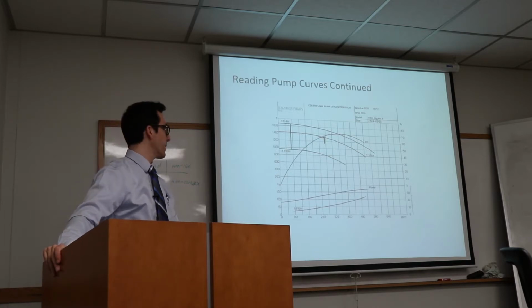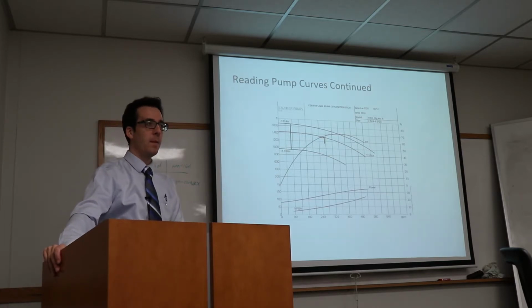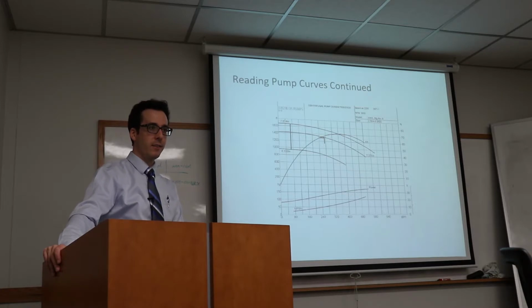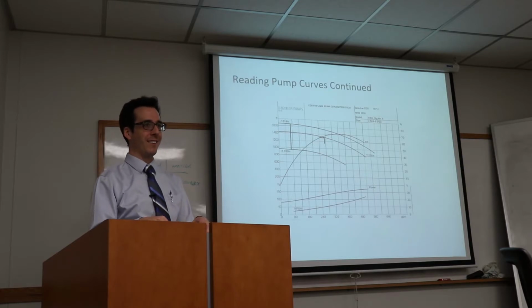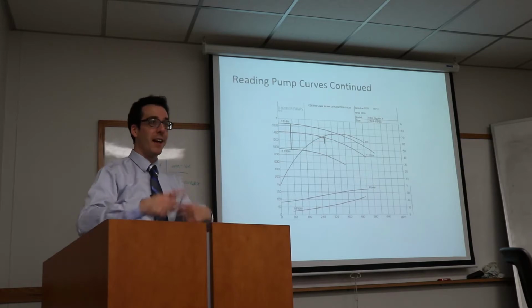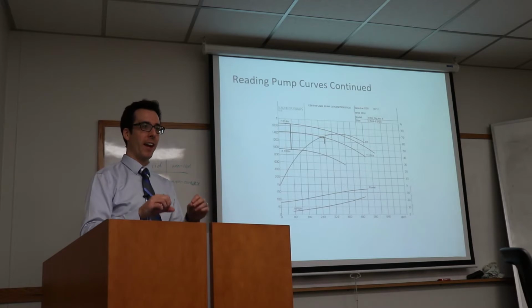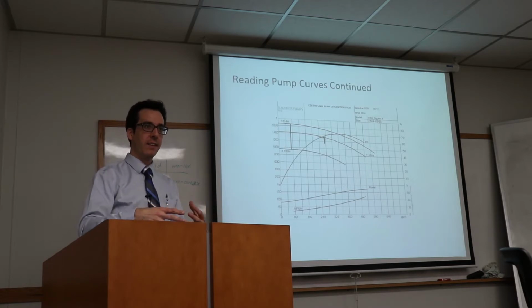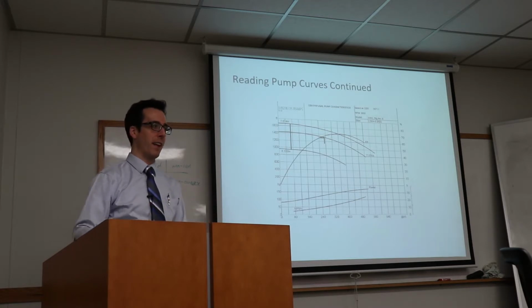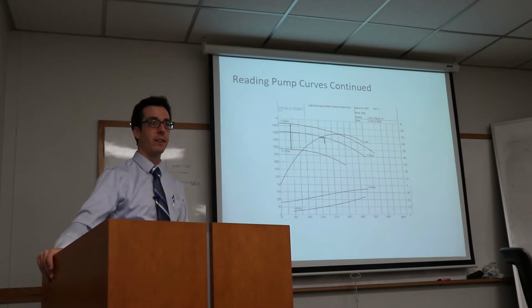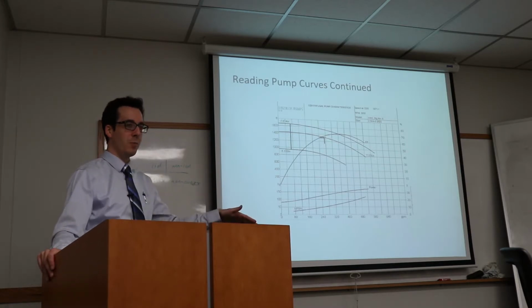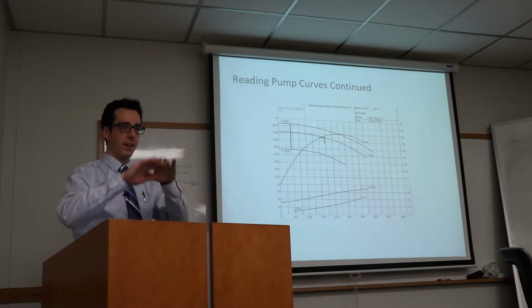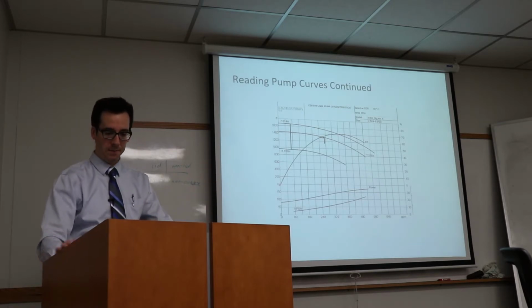At the peak efficiency, at the top of that arc, right? It's like riding a bicycle or a manual transmission car. You can tell when you're pushing a little too hard or pedaling too fast, and you want to find the right gear, the right speed to match the effort you're putting in for the speed you're going, right? And so that's what a pump curve is. You don't want it to be too little or too much, but right in the middle where it's best efficiency.